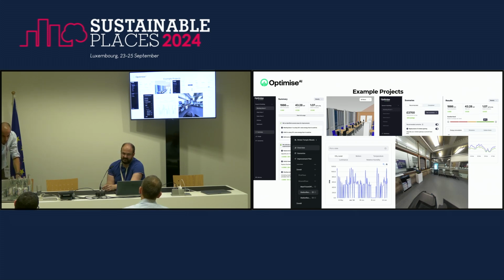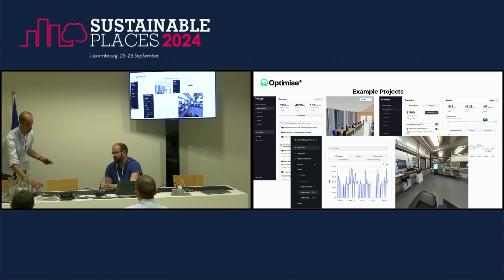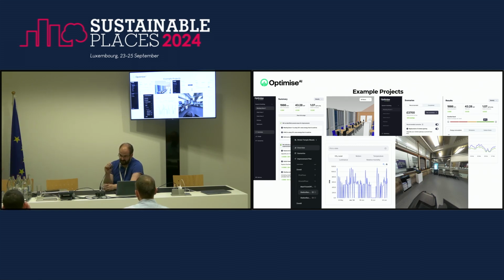We are working at integrating AI models as well, because one of the facts of an energy model is that they take quite a long time to run. It can be 30-40 minutes to run an energy model. So we look at building surrogate models. Or sometimes, if we've got a lot of historic data for a room, but it's very fine grained, like temperature in a room, it might be much more convenient to build an AI model of what we think the temperature in that room is going to be in the future, as opposed to using an energy model for that sort of task. So we're using both. Thanks.